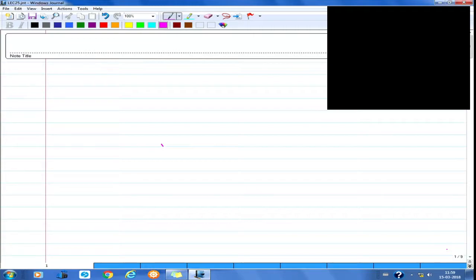So in isoparametric, subparametric is kind of embedded, but when you want to do the superparametric, and most of the time you don't want to do that, because geometries might be complicated, but then anyway you are breaking into a number of elements, and more importance is given to the field variables. In superparametric formulation you are interpolating the geometry using higher degree polynomials and lower degree for the field variables, which is often not the case. Because the geometry might be complicated, but it is not as complicated as the distribution of field variables itself might be. So one really does not use these two, sub and superparametric, it's only isoparametric which is used, and in that subparametric is actually included.